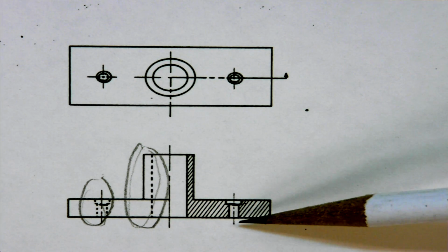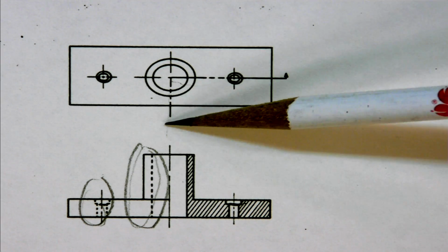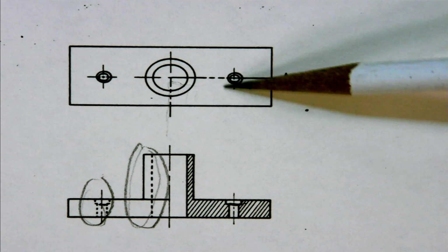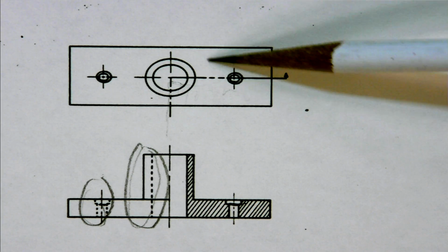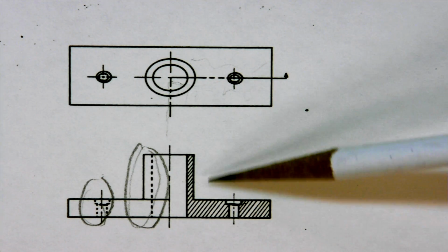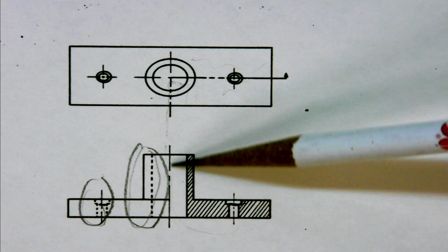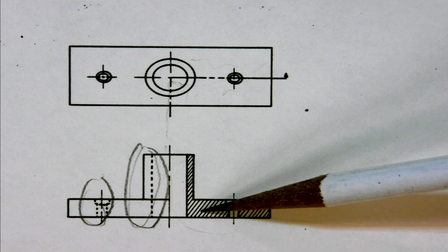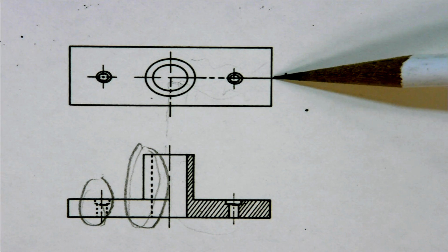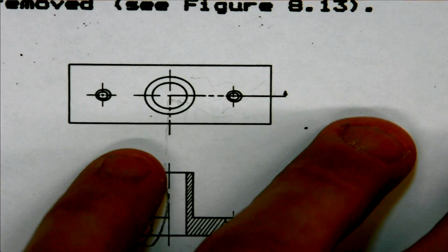The reason why is now here's your cutting plane here, going up. It's a half cutting plane. It just comes over here and takes a quarter of the object away. This is all shown as interior. This is all shown as exterior minus the hidden features. You're showing all this hidden stuff over here, and it's split down the middle with an axis line. So interior view, described by the cutting plane, exterior view where the thing has been cut, a half section.